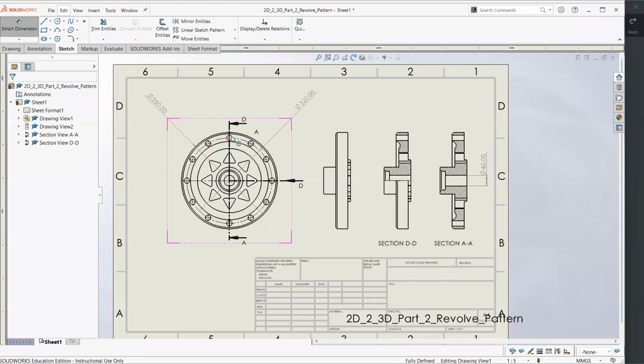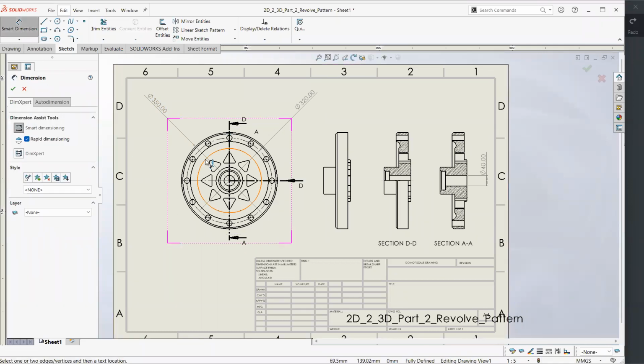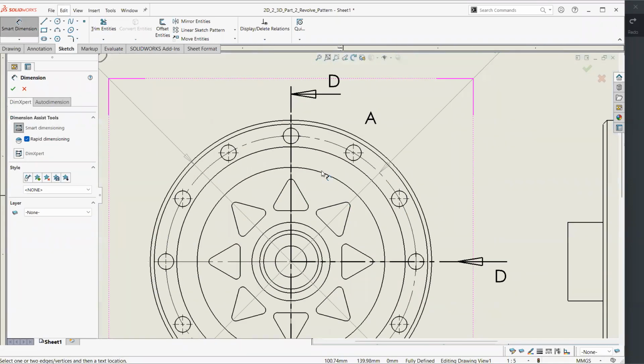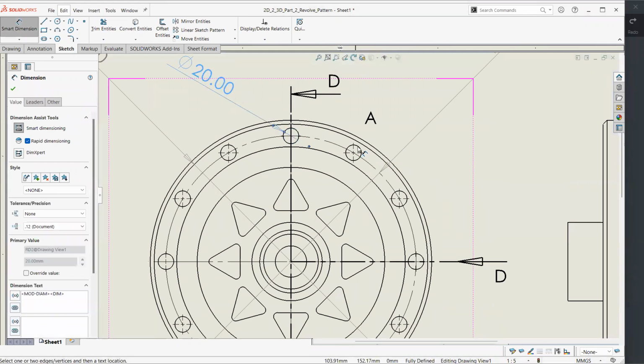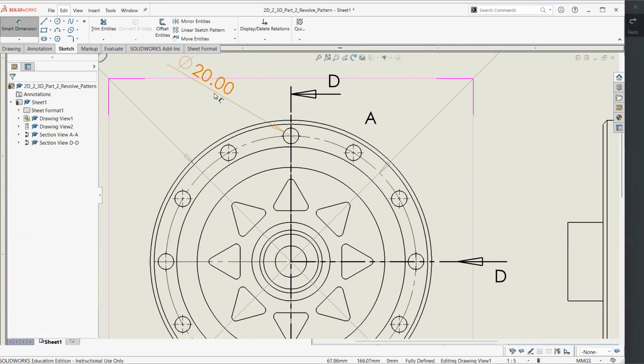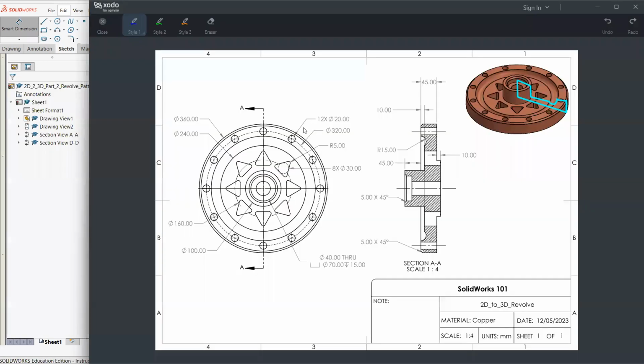So instead of simply trying to go to every circle and giving the dimensions of every circle, this will be tedious and it will not give a lot of information since all the circles have the same dimension. What we could do is simply something similar to this, where we simply say how much we have of that feature.